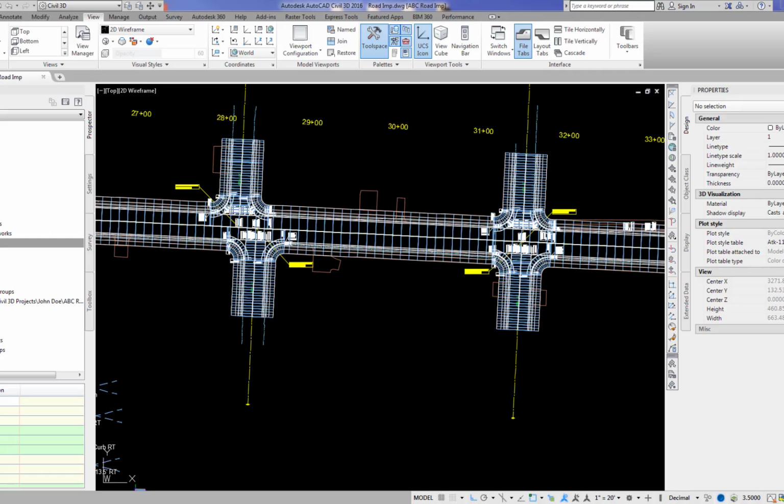Targets are used to define the horizontal distance and vertical elevation for the variable parameters in the sub-assemblies contained in the assembly for each region. The targets are automatically obtained from each sub-assembly. It is important that each sub-assembly used contain the desired targets.